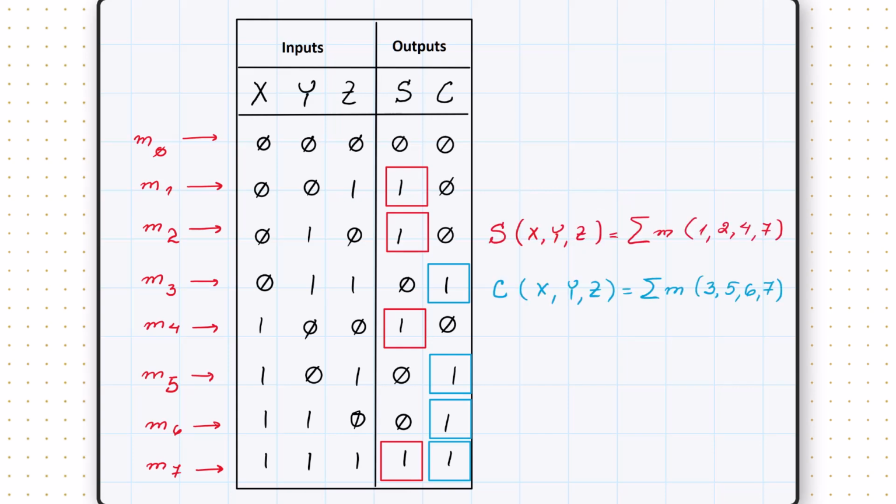Next is to move ahead with the logic circuit. We will use a rectangular symbol for the decoder. One small note in here, because we're having 3 inputs and 8 minterms, this means that the type of decoder we're going to use is going to be 3 to 8.